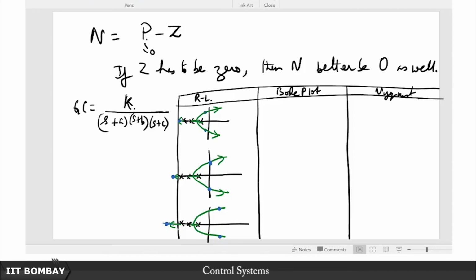So the root locus is fairly transparent, it's pretty straightforward, you can exactly see where the closed loop poles are, exact locations are obtainable from the root locus. So it's common knowledge that when your open loop system is stable to start with, initially you start at the open loop poles, so for lower values of gain you will remain in the left half plane, but for higher values of gain k there is a risk that you might go to the right half plane.